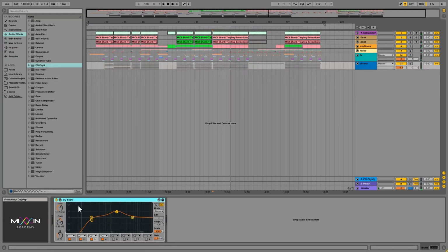Now, as you have seen, I have added this EQ. I have boosted this middle part of the frequencies close to 1K, so in between 1 and 2K, 1.5 kilohertz. And I have lowered the gain on the output of this EQ to help with level staging, that gain staging, where I can actually just disable this EQ and see if the change I made is actually better.